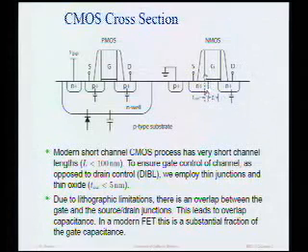Now the other non-ideality that's process induced is this overlap region. Ideally, the gate should not overlap with the source and drain, right? The gate should control the channel. Because if the gate overlaps with the drain, we get a capacitor from gate to drain, right? Okay, big deal. No, it is a big deal. That's that Miller capacitance, which we hate, which we try to reduce. And as we've made the channel length shorter and shorter, that overlap region has become a larger and larger fraction of the overall channel length. That means that the overlap capacitance, or the Miller capacitance, has gotten to be more and more important, and we'll study that in this course.